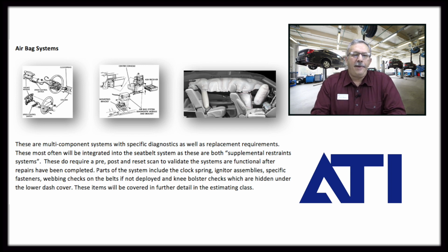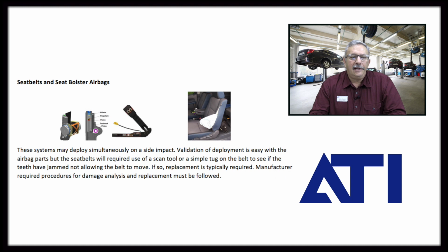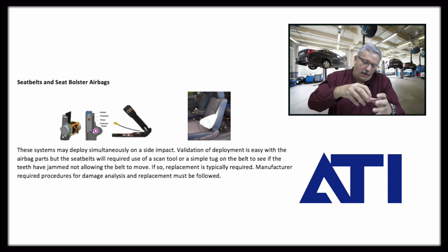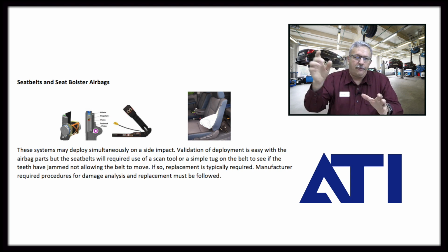Okay, we talked a little bit about seat belts earlier, but there's some additional things with seat belts, because obviously we have an explosive retractor component to these. So what are some of the things you need to consider in writing the repair plan? Number one, obviously we're going to test. You're going to go in, pull the belt, make sure that it retracts.